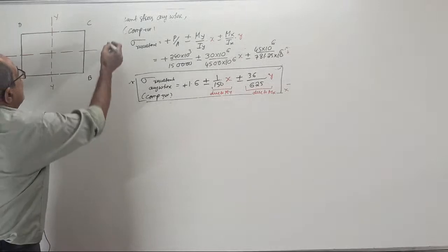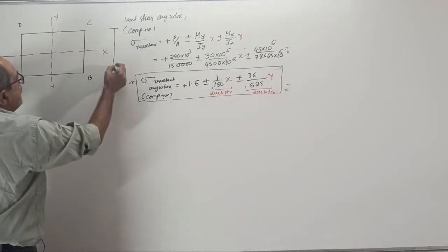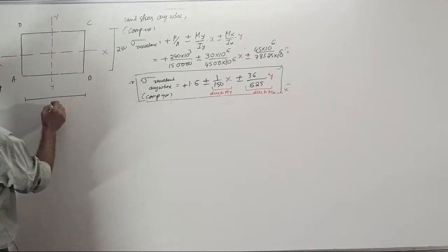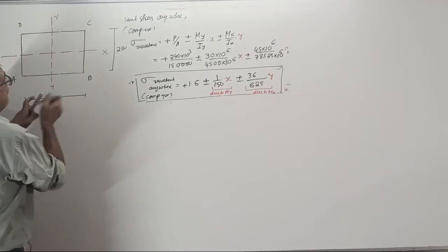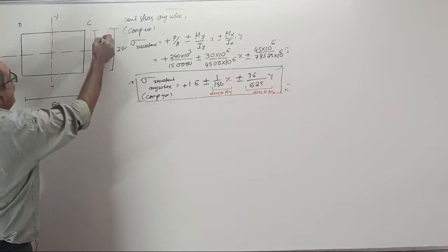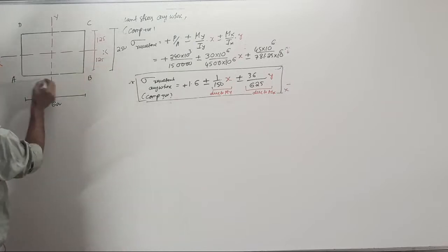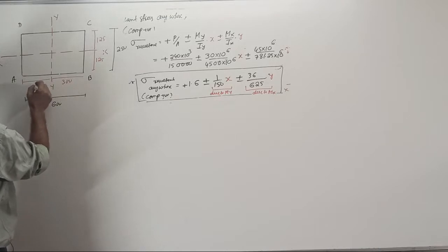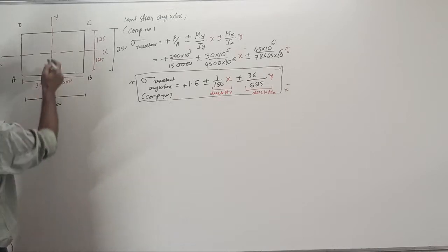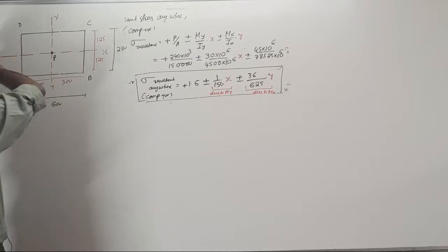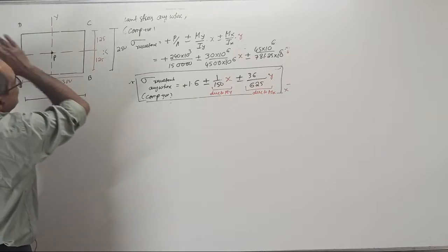See, this complete distance, if I remember, is 250. This complete length is 600. Therefore, from the axis, extreme fibers here are 125, 125. And from here, extreme fibers are 300, 300, all in millimeter. And there is axial load P here. I considered one moment like this. BM means bending moment. This is the bending moment.